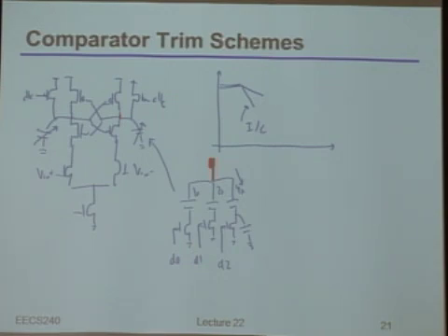The other thing I'll mention here is that by adjusting the capacitors like this, we said that our simple model showed that the slopes of the waveforms were just proportional to the inverse of the capacitance. Well, turns out I lied a little bit. The reason is that unfortunately these input devices are not really perfect transconductance in the entire region of operation.